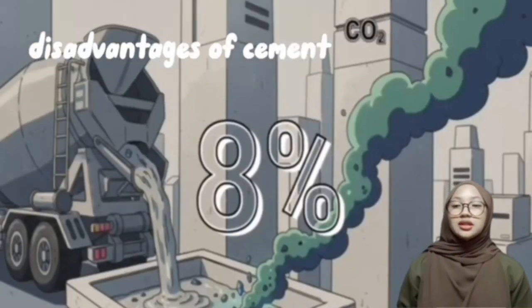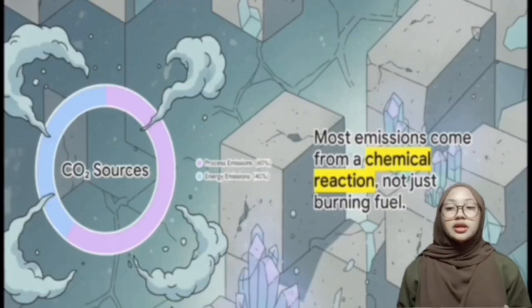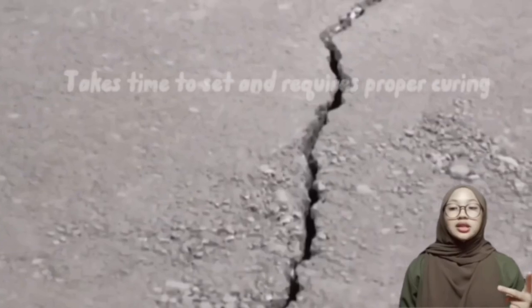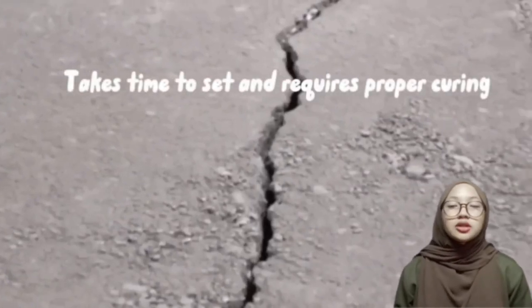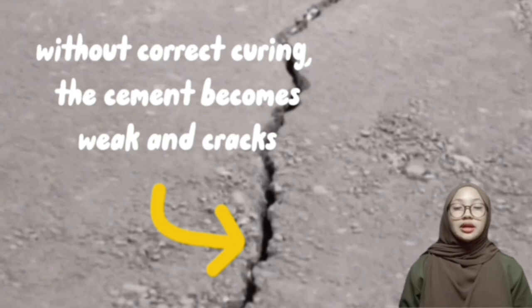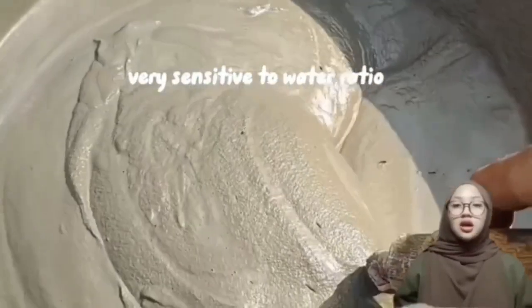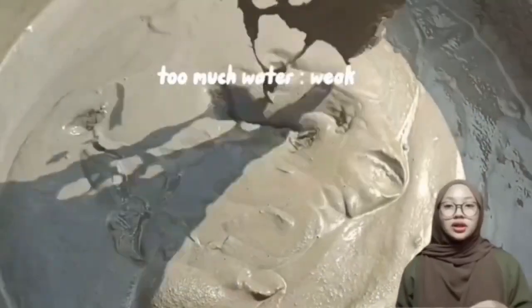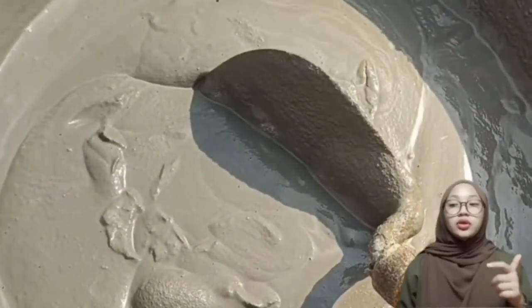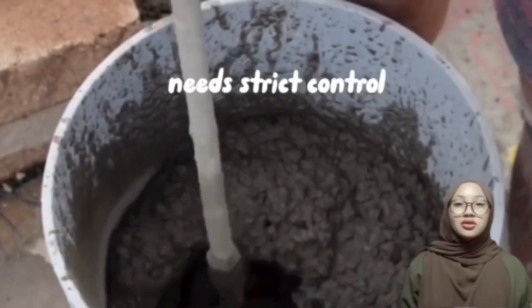Next, the disadvantages of cement. The first is high carbon dioxide emission during production, which means cement manufacturing is one of the major contributors to carbon emission. The second one is that it takes time to set and requires proper curing, because without correct curing, the cement becomes weak and cracked. The third one is that it is very sensitive to water ratio. When we put too much water, it will be weak, and when we put too little water, it's hard to mix, so it needs strict control.